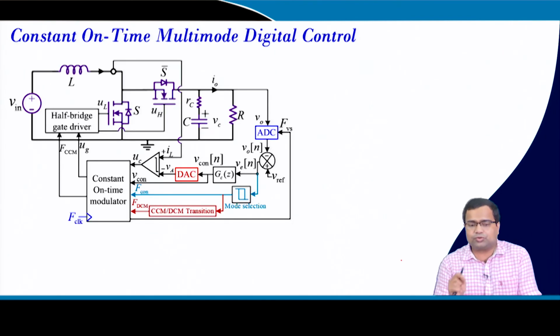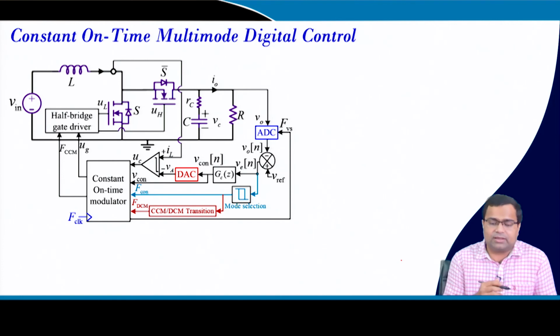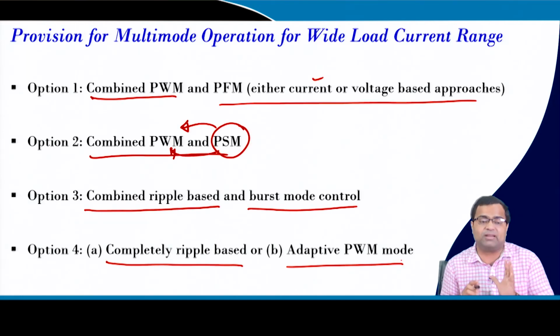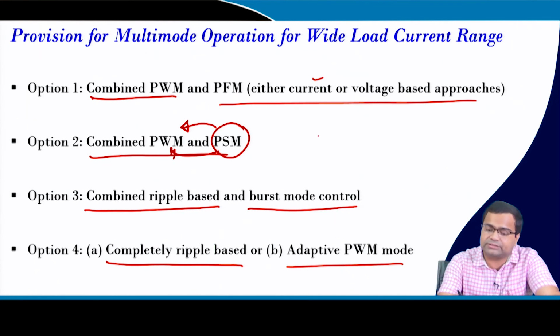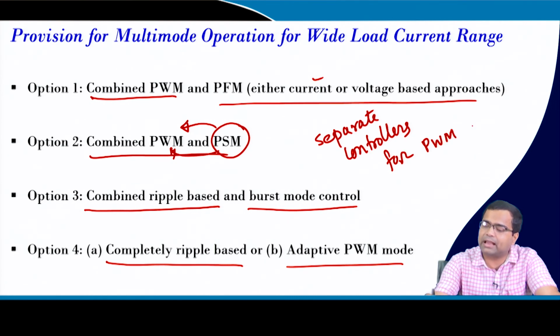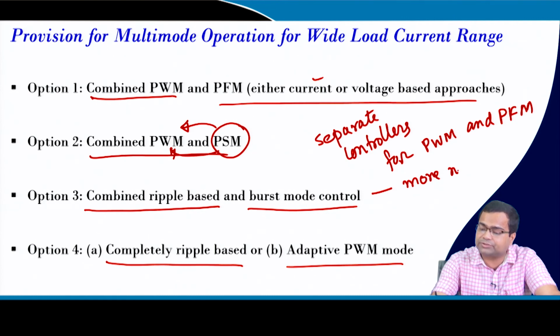Okay. So, I want to show one of the works that we have proposed here. Most of the problem in this multi-mode approach is that they use separate controllers for PWM and PFM. As a result, what are the drawbacks? More resources are required, and there can be a wind up problem when you change from one controller to the other controller.